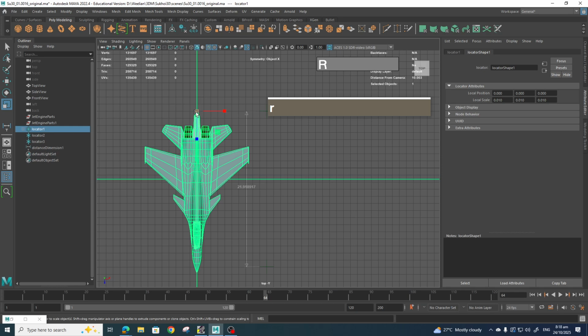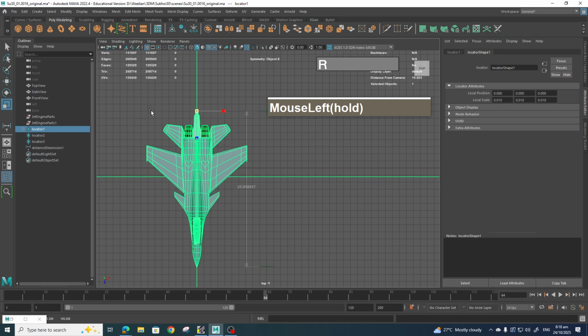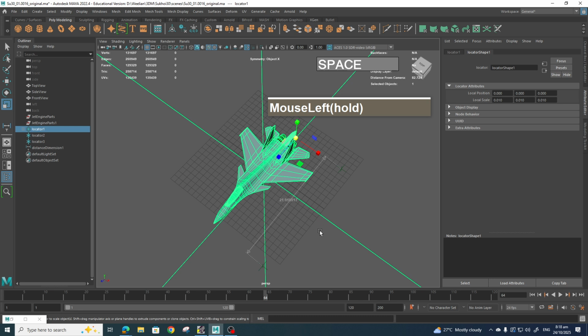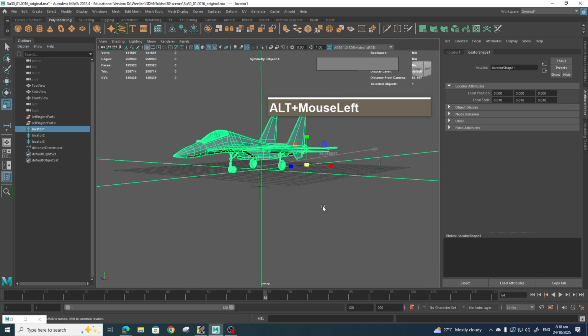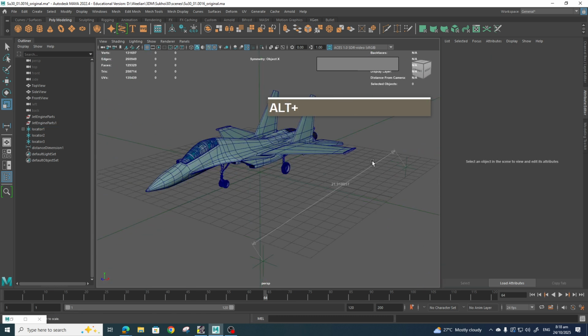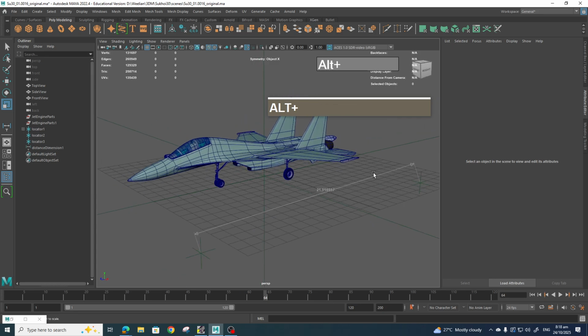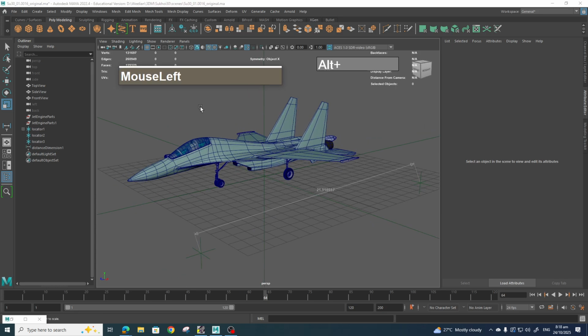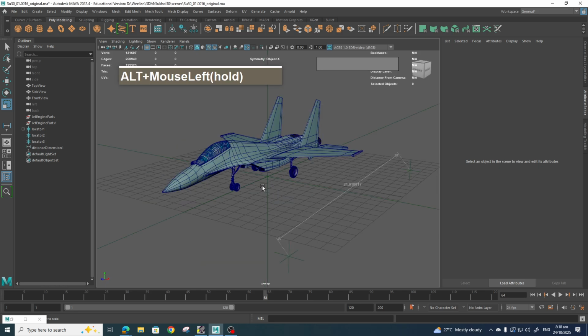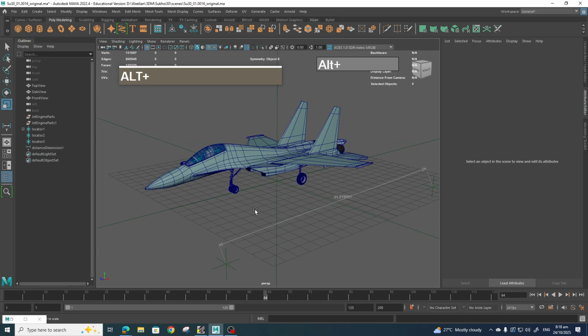So I'm going to scale it one more time until it matches the tail, and the nose matches the distance. So now I get the aircraft right to match the dimensions. Again, I have to emphasize why this is so critical. In a lot of production pipelines, the scale is very important. In the past, I never really went through this with my other students. So when they create their models separately, and then put them together, all the scales are all over the place.